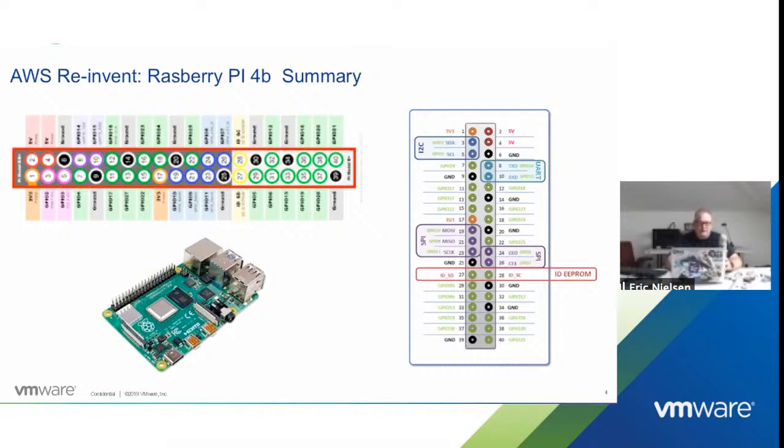So what I would like to talk about is the pins and GPIOs. General purpose IO, all of these pins can be used. Even though they have different color codings, anything that says GPIO on it is a general purpose IO. I can hook a sensor to a general purpose IO pin. But there are special pins that are reserved for various protocols. The Raspberry Pi supports and has libraries for certain protocols. The most famous protocol is called I2C, and I'll talk about what I2C is later in the slides. But that's a bus protocol, and we have a data line and a clock line.